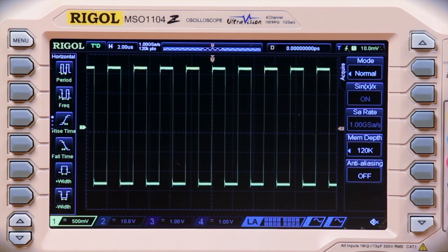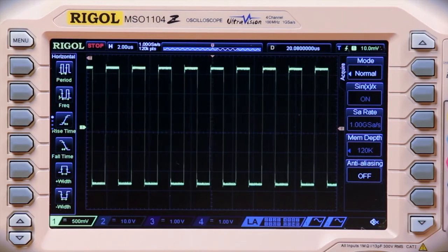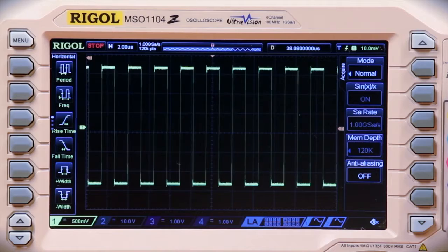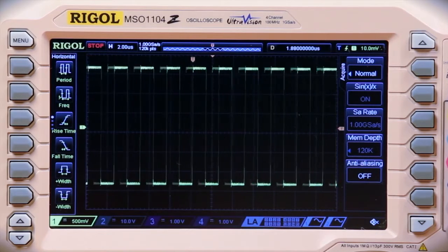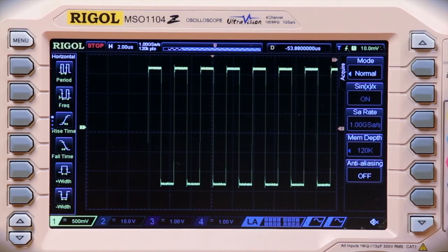This is especially important when using the deep memory of the oscilloscope. Once you stop capturing waveforms, you can then move to view parts of the waveform that are originally off the screen. Triggering is a reference point for how we compare and evaluate signals. Understanding the basic concepts and different methods of triggering makes signal analysis more effective.